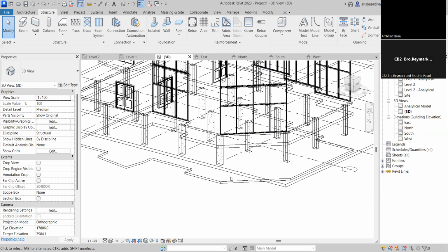If we are working in level 1 in architecture, usually when we create a wall, our wall is coming from level 1 up to level 2, upwards. In structure, when we create a column and we are in level 1, automatically that goes down, in the sense that the structural is always supporting the architectural model. So, for example, if we are just doing an individual file without linking the models and you're in level 1, you can create the wall, and at the same time, you can create the foundation for your wall. That's how they made it work this way.